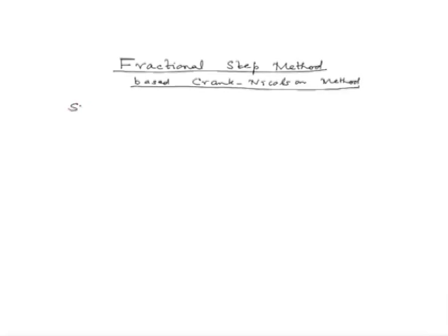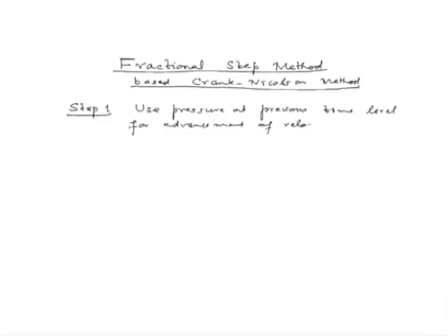So, now our step 1, what do we do in step 1? We would use pressure at the previous time level for advancement of the velocity field.